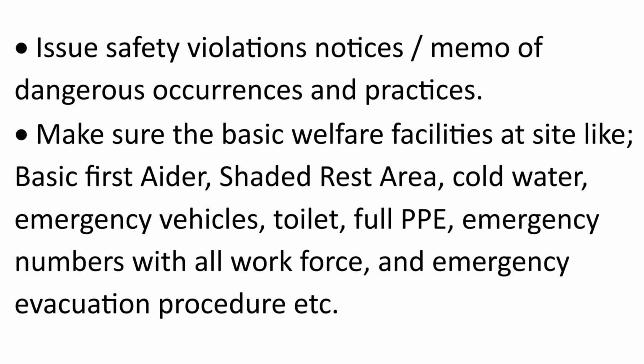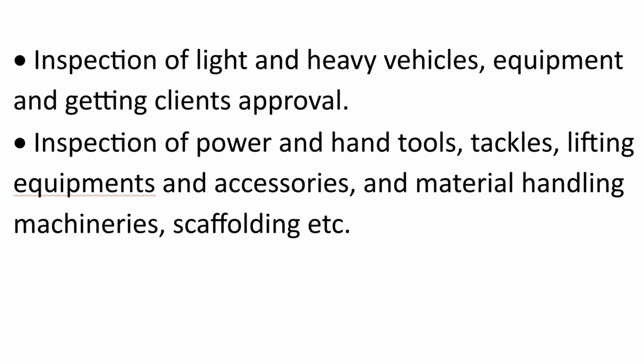Issue safety violation notices and memos of dangerous occurrences and practices. Make sure the basic welfare facilities at site are available, like a first aider, shaded rest area, cold water, emergency vehicles, toilet, full PPE, emergency numbers with all workforce, an emergency evacuation procedure, etc. Inspection of light and heavy vehicles and equipment and getting clients' approval.